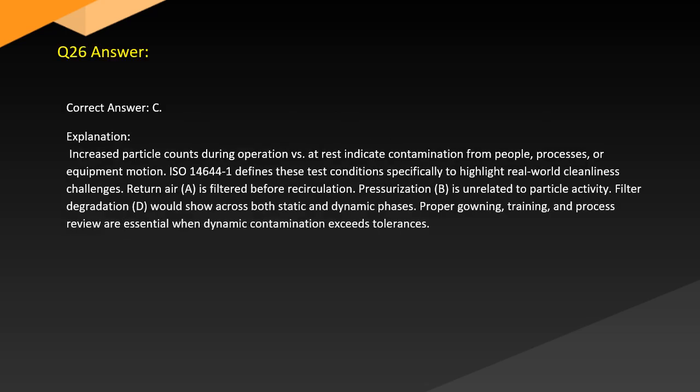Answer. Correct answer: C. Explanation. Increased particle counts during operation versus at rest indicate contamination from people, processes, or equipment motion. ISO 14644-1 defines these test conditions specifically to highlight real-world cleanliness challenges.